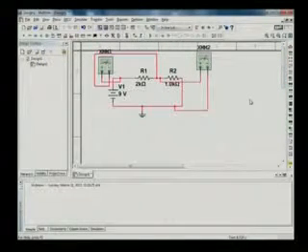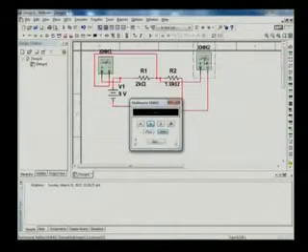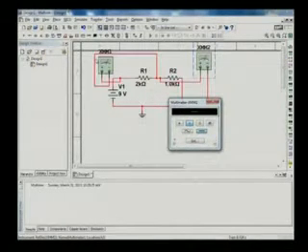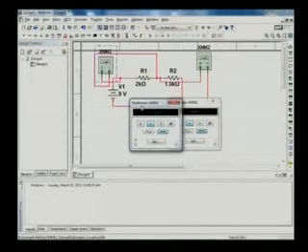This circuit is completed. So theoretically, the voltage across R1 will be 2 divided by 2 plus 1, that is 3, into 9. So 2 divided by 3 into 9 will be 6. Similarly, the voltage across R2 will be 1 divided by 3 into 9, so we will get 3. That is theoretical. Double click and we will check whether it is showing the correct answer or not.